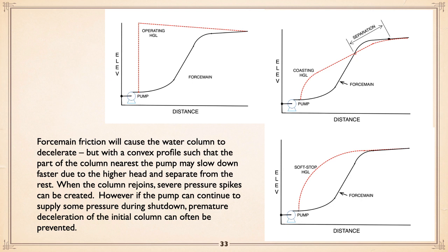Now, when you've got soft stop, using a solid state starter, you actually can apply energy to the force main as you're ramping it down. Therefore, the line comes down nice and steady, and as you can see here, once it hits that point where everything is nicely stopped to the elevation, then you can turn it off because there's no fluid flow and everything's great.